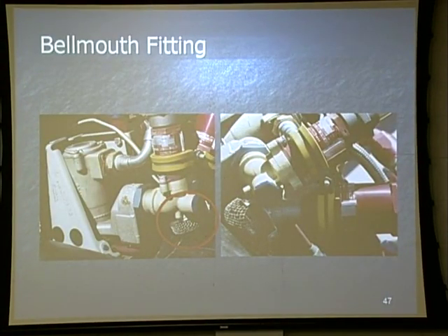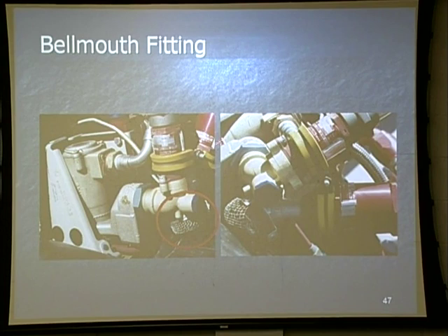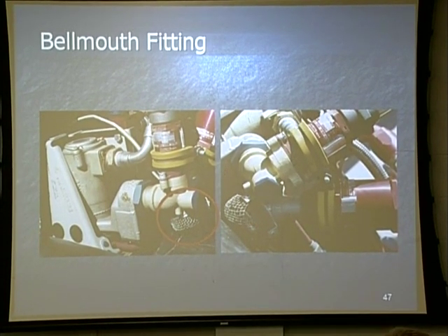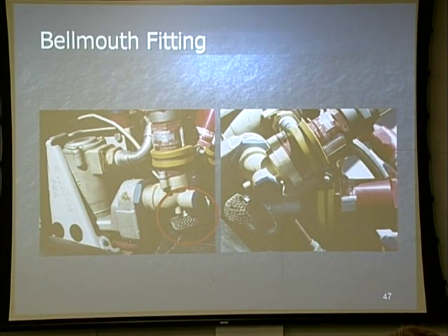And we'll show you more. There's that bell mouth fitting, and you can see that there's a line that comes in. This is back there in the main tank, right next to the aft pump. Why is it important to understand, gentlemen, where that bell mouth fitting is? What is the bell mouth fitting actually for? That is where your engine-driven fuel pump is actually sucking fuel out of its associated main tank.